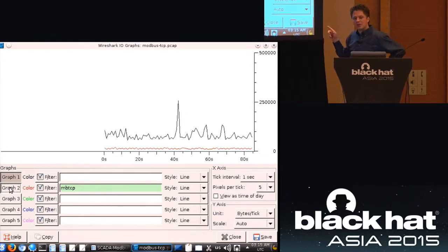And this is important to note because if you ever work with control system traffic, it is highly predictable. It almost always looks the same. You should see very, very consistent behavior in almost all your control center protocols, which means if you're a defender trying to build security defenses around a control system, you can usually do anomaly detection on the network traffic to determine if you have some strange attacker inside of the infrastructure. Because an attacker's profile is going to look very different than your normal profile. And you can whitelist fairly easily most control system traffic if you have the right equipment to do so.